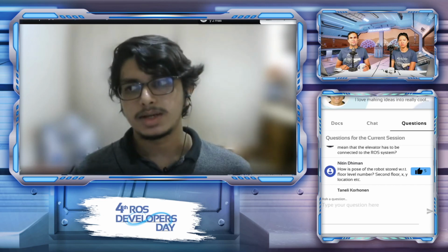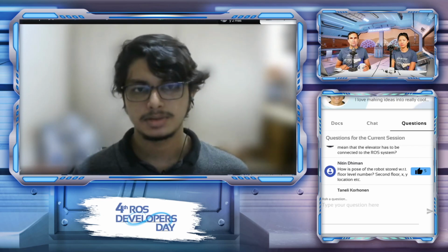So when creating the map, we only need to map out the different areas which are different in structure. That covers the lobby and the floors which are unique. Once I have a single map for the floor, then I don't need to do it again for all, suppose the building is of 50 floors. I know the basic structure of the area is the same. When I run it in there, if there are some differences or obstacles, they will be covered in the local costmap. The global costmap is going to be the same. So that is not a problem. Exactly. Makes sense.